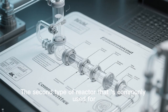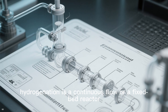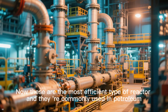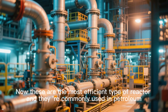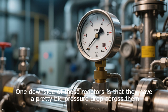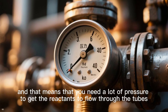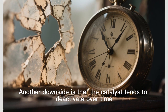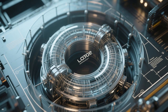The second type of reactor that is commonly used for hydrogenation is a continuous flow or a fixed bed reactor. These are tube-shaped reactors that are packed with the catalyst and the reactants flow through them. Now, these are the most efficient type of reactor, and they're commonly used in petroleum refineries and other large-scale operations. One downside of these reactors is that they have a pretty big pressure drop across them. And that means that you need a lot of pressure to get the reactants to flow through the tubes. Another downside is that the catalyst tends to deactivate over time, and that means that you have to replace it regularly.